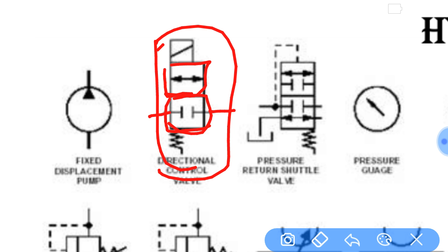So it is basically a two position direction control valve, and you can see at this position these connections are blocked, and at this position these are connected. These two lines are connected. So we can easily understand that if we take this position here by some actuation, then there will be flow, and at this position there will be no flow, it will be disconnected.